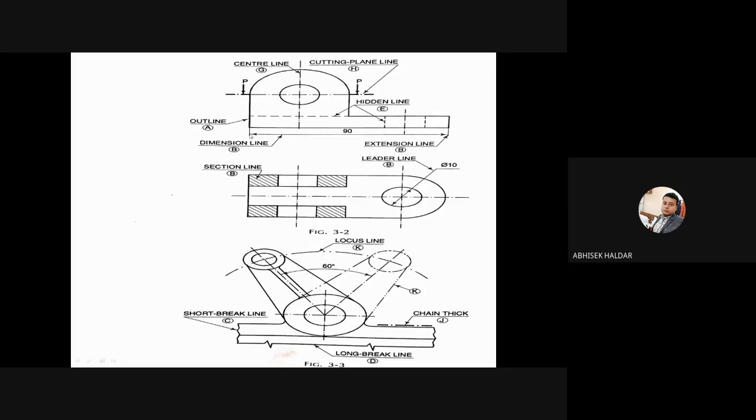It should not cross the extension lines, or be shorter; it should touch this extension line and that one also. Once you have drawn this dimension line perfectly parallel to the object, write the dimension at the middle and above the line, not below the line, and not somewhere else. That is the way of dimensioning.